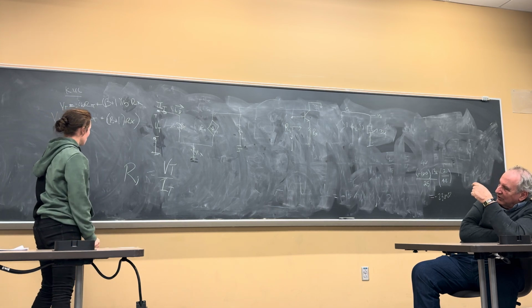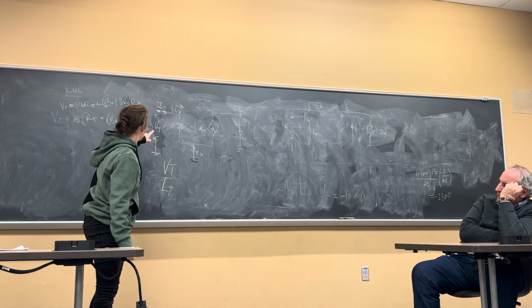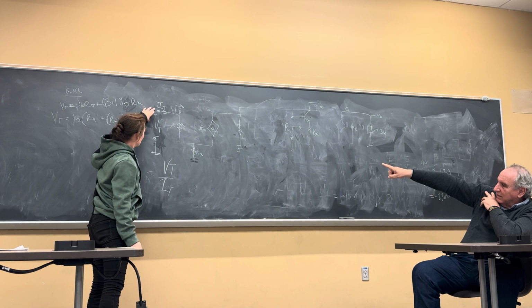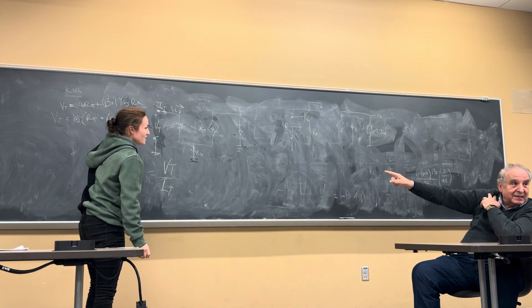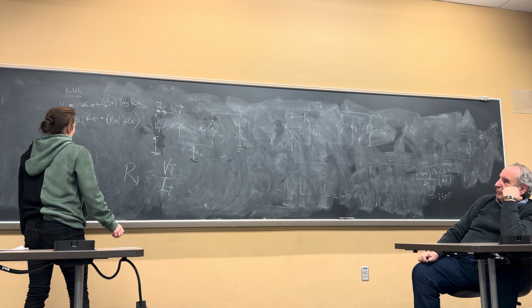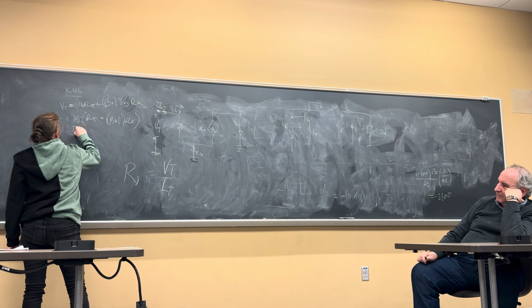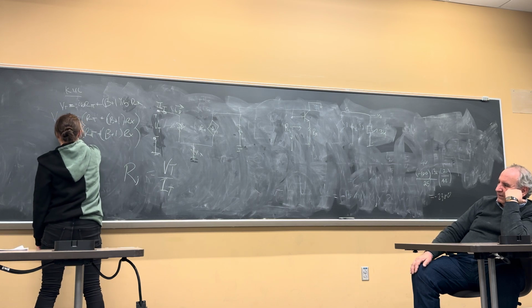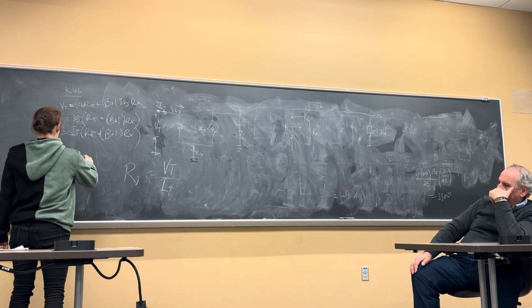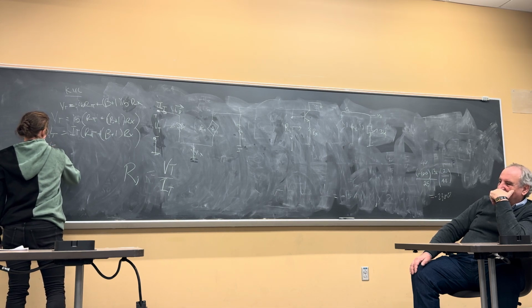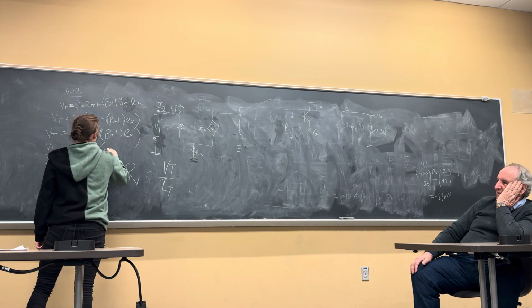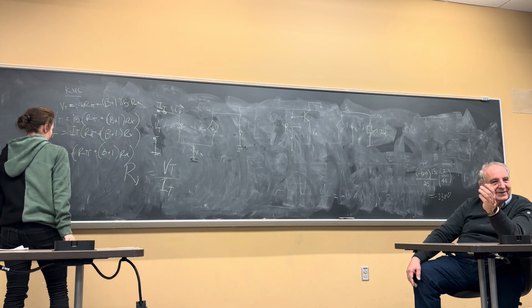Look at the circuit, VT equal to IT, correct? Up there, where I put IT. It's equal to VT, equal to IB. I'm looking for VT over IT, this is Rn. So take the IB out and put IT on it. Equals VT, right? Now VT over IT will be equal to Rn. It's equal to R pi plus beta plus 1 Rx, right? That's the impedance reflection, that's the input impedance.